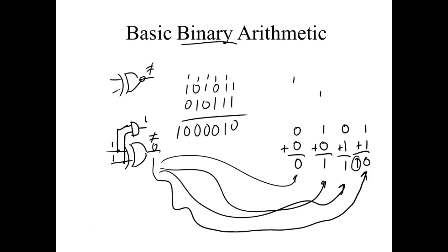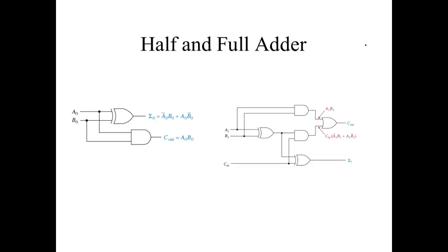Does that make sense? So if I was going to try to add this plus another number, then I've got problems because this circuit only does that right there. But what I would do is, let's say I got 1, 1, and then 1, 1. Well, this circuit would do this, but it would have a problem with the next bit, right? You understand? Because I've got to be able to bring a carry into the next bit. So this would be the one I just did. This is called a half adder, and then this right here is called a full adder.